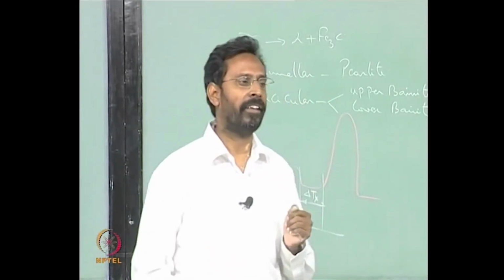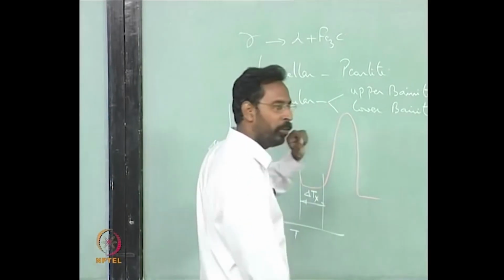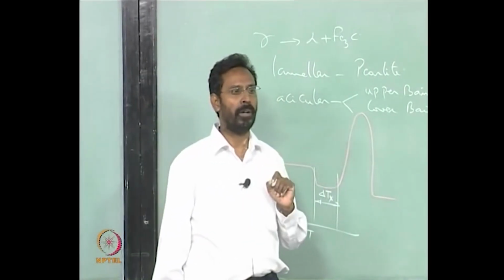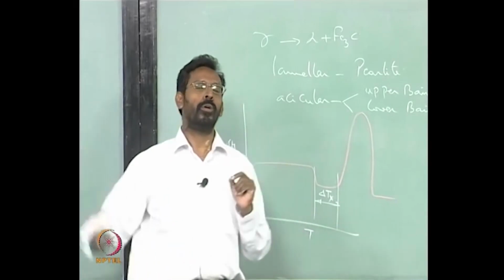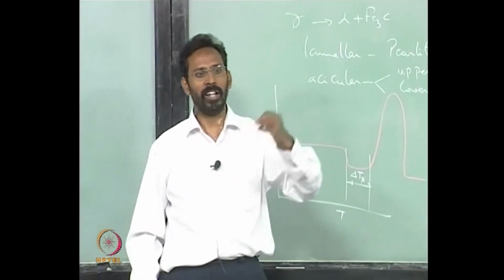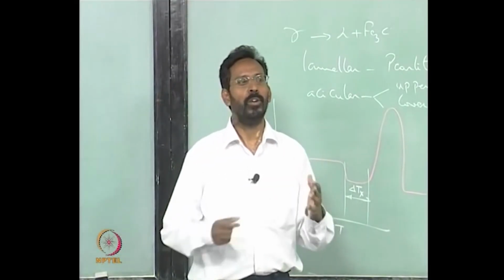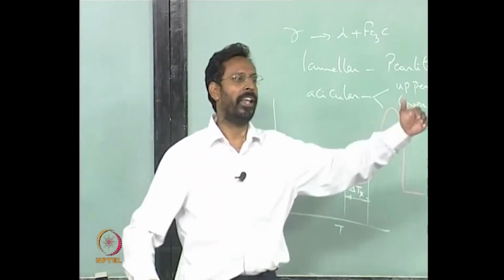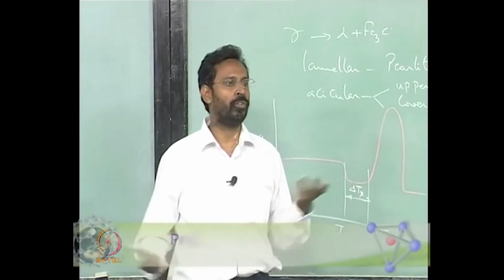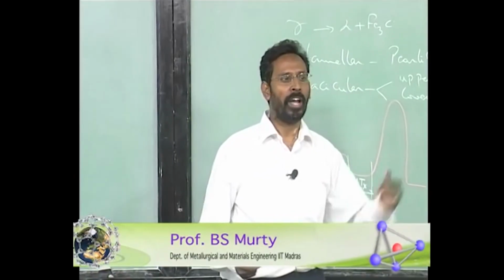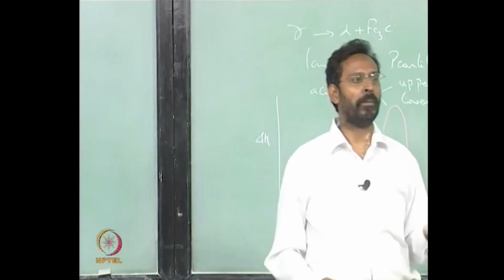There are examples like that, where basically you induce small nanocrystals, so that small shear bands form and then there is no growth of that. Because each particle will act as an obstacle for the shear band to grow. So as a result you have obstacles for any crack propagation, and that gives you higher fracture toughness. Fracture toughness is always related to either crack initiation or crack propagation.